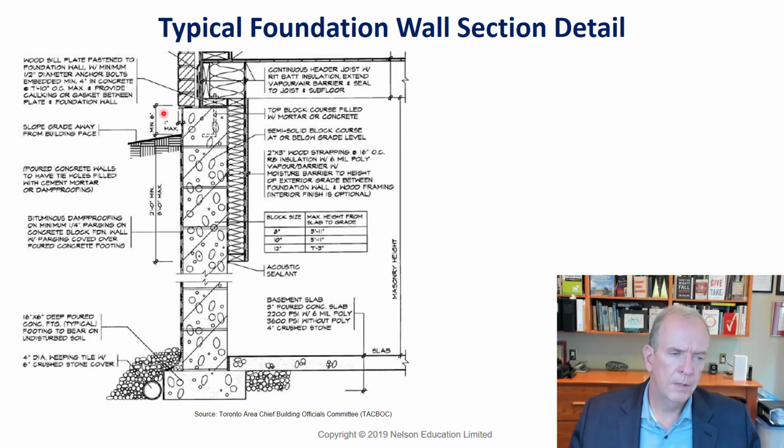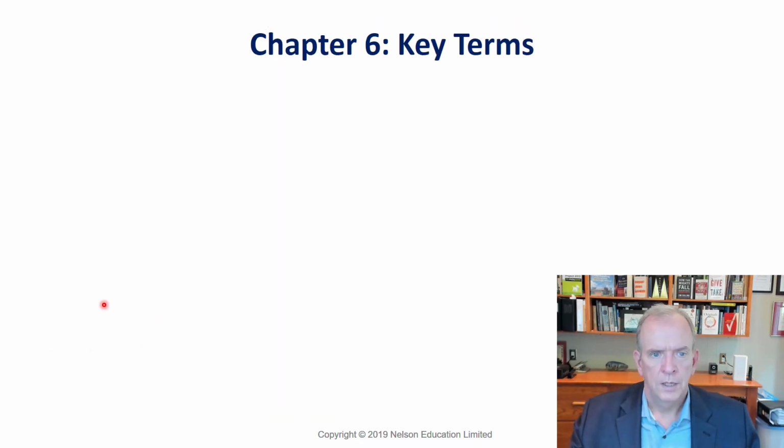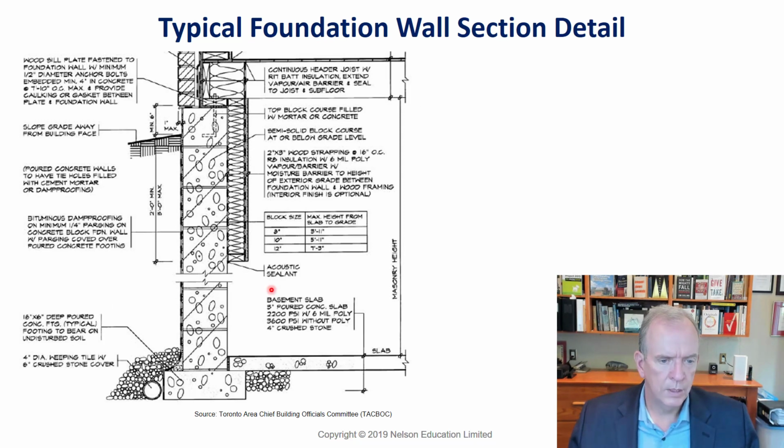So with brick, we've got a minimum of 6 inches above grade building code requirements. You can see the gravel underneath the slab here, as I mentioned, the gravel over the weeping tile here, and the drainage layer material put down across here. And this detail, by the way, is a little bit older than the previous one. I noticed that this doesn't go all the way down to the foundation. Now they go all the way down to the foundation because we want to insulate all the way down. So this one's a little bit dated as codes continuously upgrade.